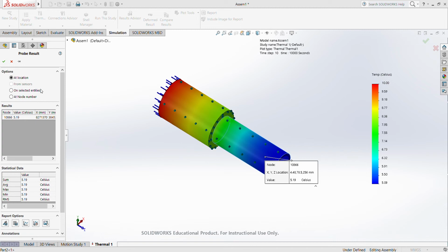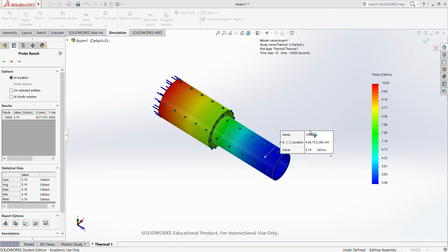So I might want to refine the analysis because I want to know what's happening here. This is basically telling me that by 1,000 seconds we're already. You can see this actually went down colder. By 1,000 seconds we were already at temperature. So we might need to refine the temperature increment.